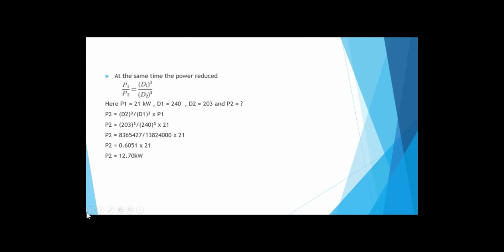The pump discharge increases under such operating conditions, and the motor is likely to get overloaded. So one of the ways to resolve such a problem is to trim the impeller at site to suit actual operating conditions, or install a VFD. VFD is nothing but variable frequency drive. Installing the VFD reduces the speed of the pump.